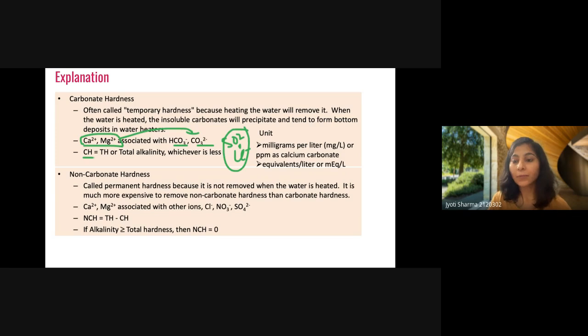So carbonated hardness will equal total hardness, or alkalinity will equal total hardness, because here the only associated anions are carbonate, not sulfate or chloride.